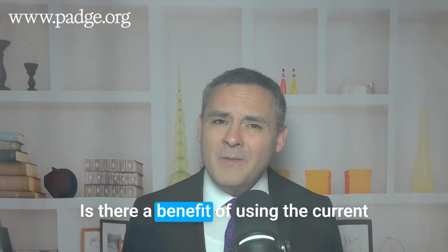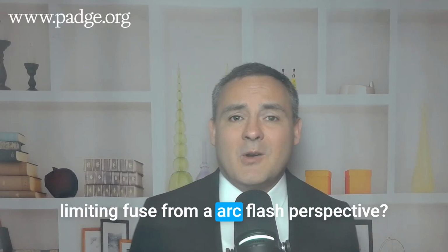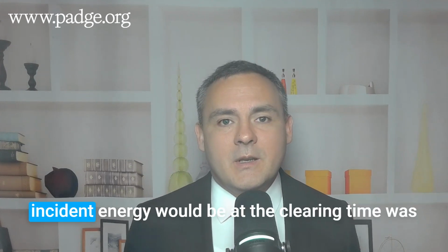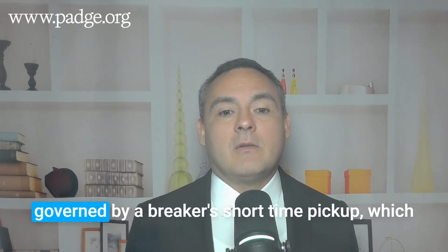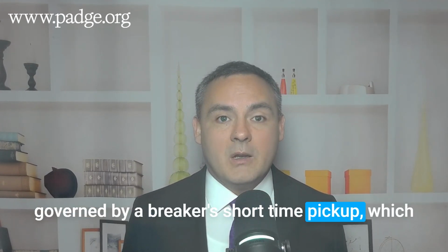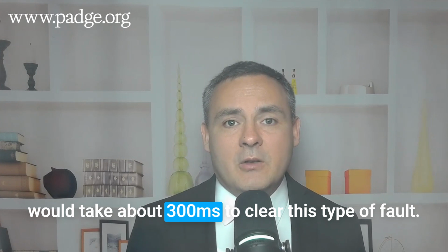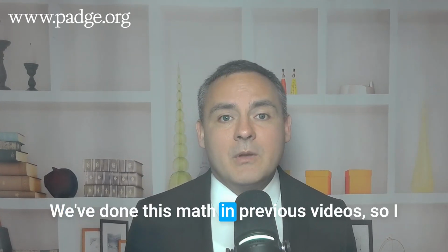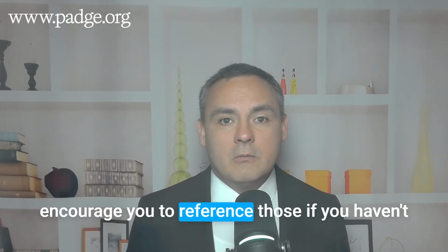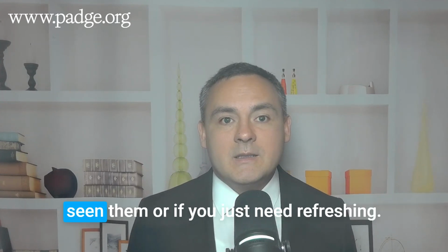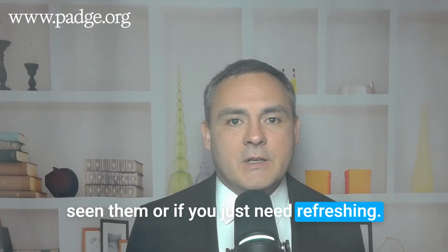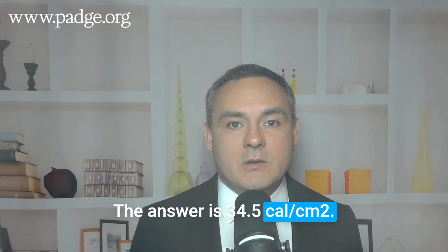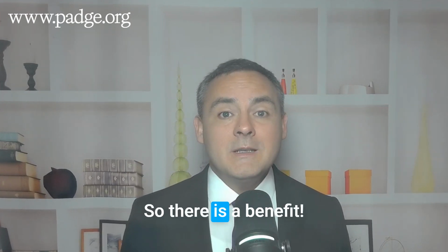Is there a benefit of using the current limiting fuse from an arc flash perspective? Well, we would need to calculate what the incident energy would be if the clearing time was governed by a breaker's short time pickup, which would take about 300 milliseconds to clear this type of fault. We've done this math in previous videos, so I encourage you to reference those if you haven't seen them or if you just need refreshing. The answer is 34.5 calories per centimeter squared. So there is a benefit.